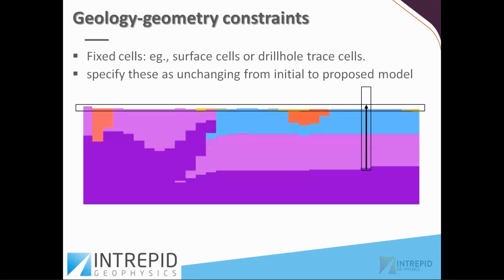The key considerations in the inversion setup are that we set the model resolution and the number of iterations at the initial stage of inversion. We can set the geological constraint set as per lithology. Then we can also set the lithology rock property values under distributions. Then we can prepare the geophysical grids, and set the survey precision of the geophysical data. Here's the summary of the bed inversion evaluation misfit.